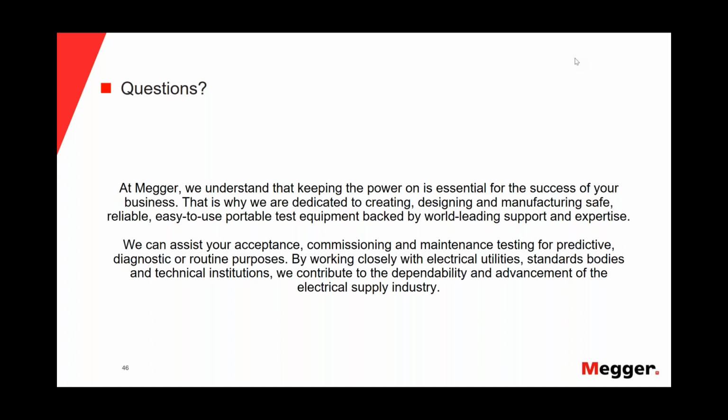It's the same like, you know, when you do factory testing on cables, you're testing at a very different level, because when the cable is new, it must take a whole lot more, so it can, under normal aging conditions, still function after 30 years, okay? So that's the biggest difference.